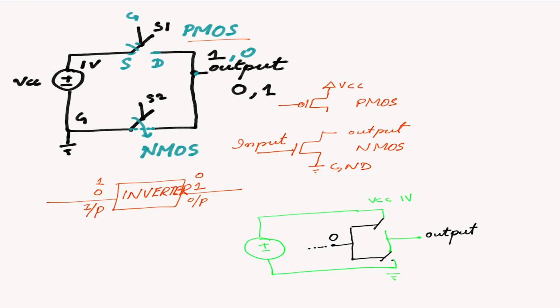So when we want 0 here, as an inverter, it needs to generate 1 here. So 1 means supply voltage. Okay, so when 0 is here, we want this top switch to conduct. So when this node is connected, this switch is on, this is connected to the VCC, and we have 1. And when we have 1 at the input, we want this switch to conduct and the other one to be open. In this way, this node will be connected to 0.